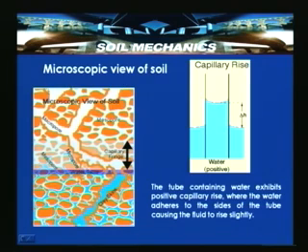So, here in this slide the soil microscopic view is shown. What has been discussed is that the soil can have interconnected pores of different spaces. These pore spaces or pore channels can be in any direction and can be of any shape. We have discussed that it is very difficult to simulate that, but to understand the behavior, to a great extent this capillary tube behavior closely represents the behavior which occurs in nature.